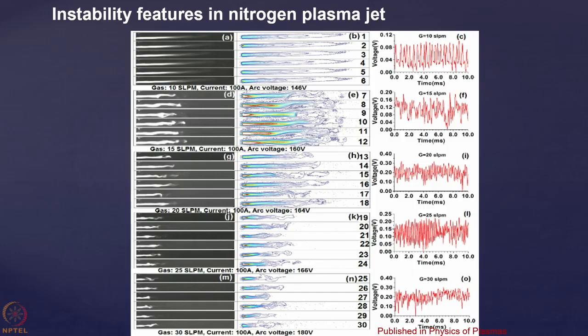So that is something to be understood very well, how the electromagnetic body forces are playing the role, and those body forces are again driven by the current and the thermophysical properties of the plasma. So what ultimately matters is that, together with the thermal field, the electromagnetic forces and the fluid dynamic effects act together and make the overall behavior you are observing.